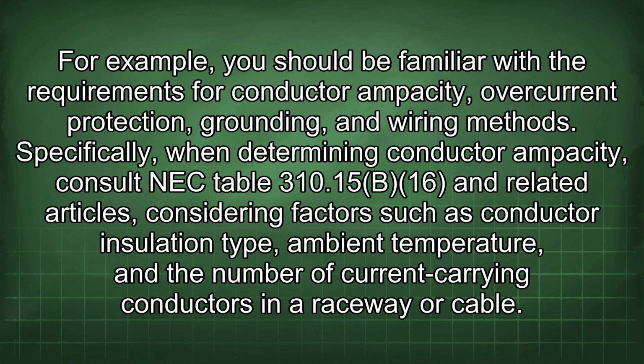Specifically, when determining conductor ampacity, consult NEC Table 310.15(B)(16) and related articles, considering factors such as conductor insulation type, ambient temperature, and the number of current carrying conductors in a raceway or cable.